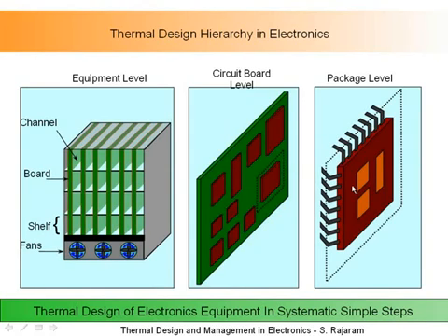And then from these packages, you've got these leads. These leads can be of different materials, copper alloys, aluminum alloys, etc. And the heat from here is dissipated through the package, through the leads, into the board, and carried out by the air through convection. Now, if this is a product that is in space, where this can be a solar wing, essentially you've got radiation.